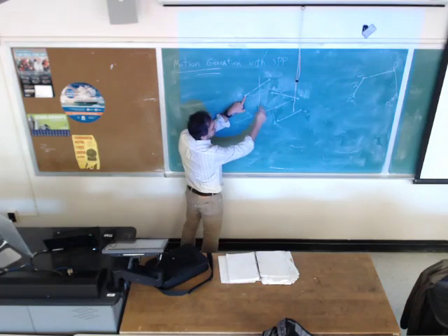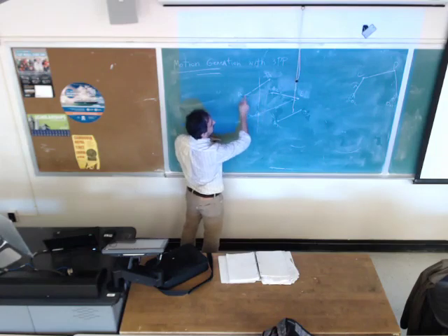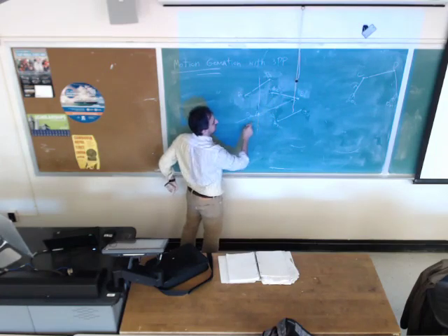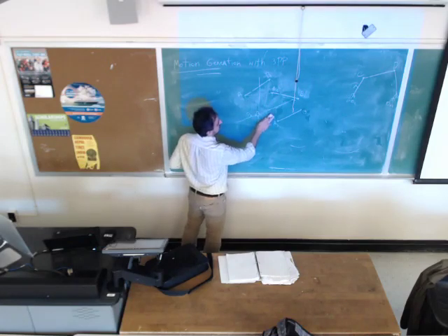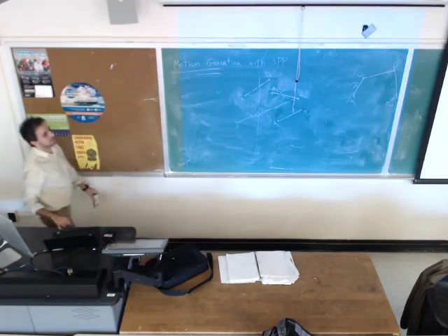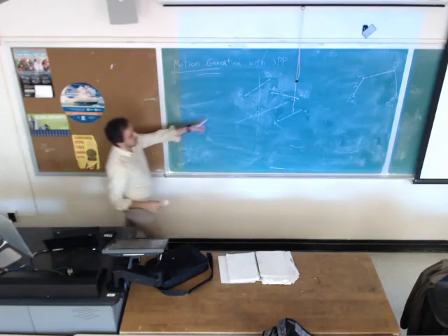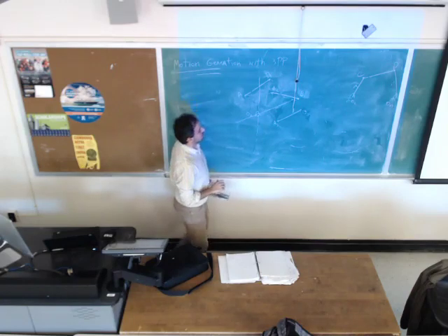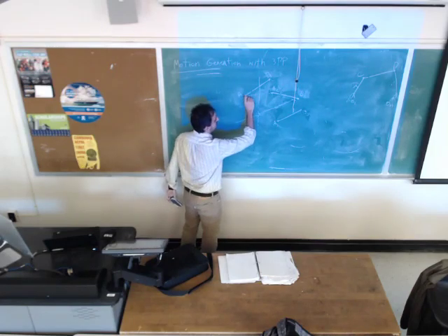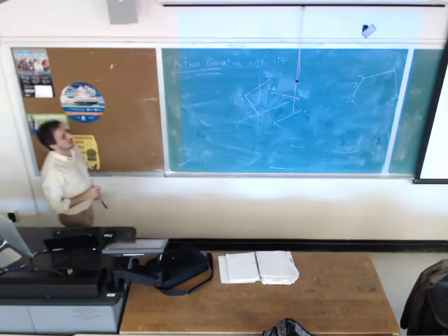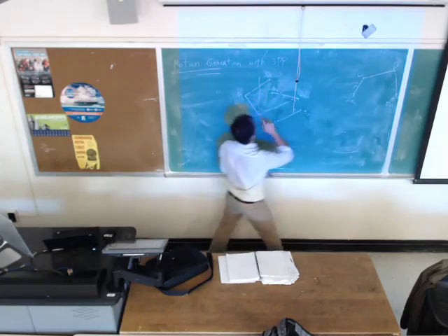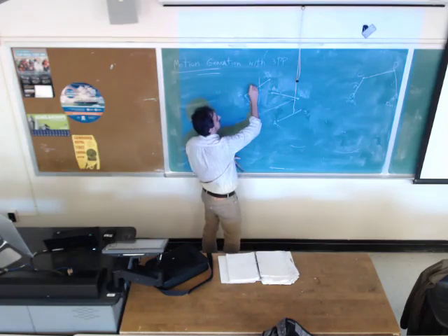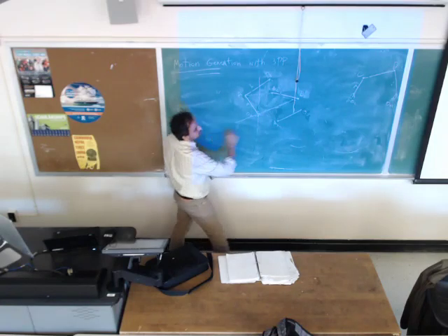You might say, why didn't you choose A1 and A3? We can prove that if we draw A1 and A3 and draw the perpendicular bisector, it's going to pass through this point. We don't go through proving that, but it's true. So this is the location of O2. If I connect this to this one, I'm going to get O2 to A1. It's going to be the A. It's going to be B. I should find the location of O4.